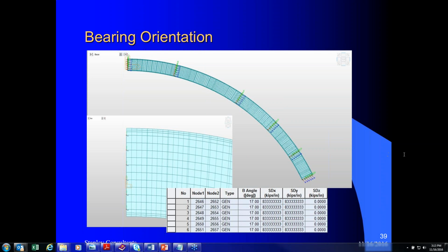Another question: a rigid link would force the beam to have the same curvature as the deck, causing high forces in the cross frame since web flexibility is not modeled. Okay, yeah, that is true. That results in higher cross frame forces; it makes it a little bit flexible.